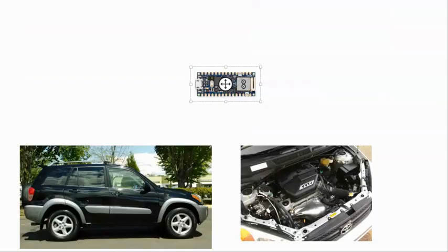So first we're going to connect this to a PC, and then we're going to put the Nano RP2040 on the engine, and then we will record normal operating vibrations, in the hope that if we create an abnormal vibration later, it should be detected by the machine learning model that we will train in Edge Impulse.